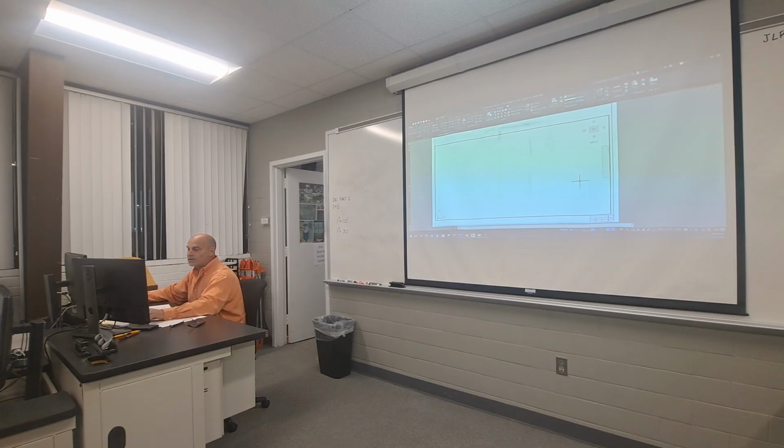Alright, so the way we set those scales up down here in AutoCAD, as I said, we do not have the scales we need. In my classes, never use these ratio scales, for those of you that haven't heard that a dozen times yet. Our engineer scales are not shown down here. If you're doing this inside your master drawing that's for several classes, whether it's mine, Mr. Spooner's, whoever, if you've got these border and title blocks all in one master drawing file, we're not going to hurt anything for any of your other classes. We can delete scales off the list, but we're not going to. We're leaving all of those on there.